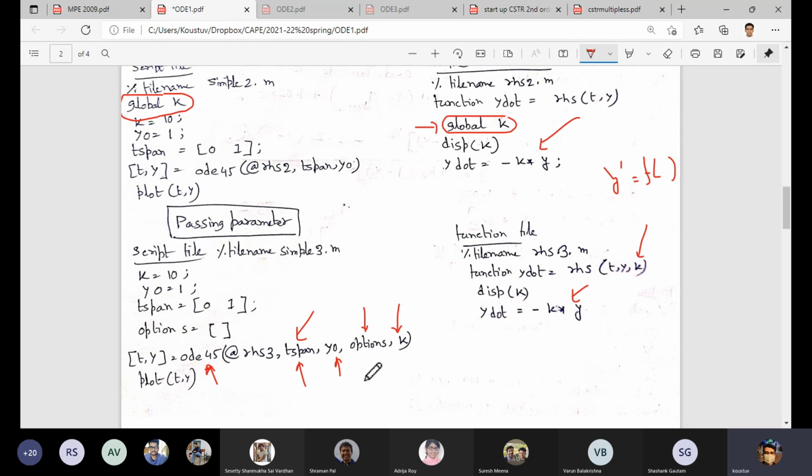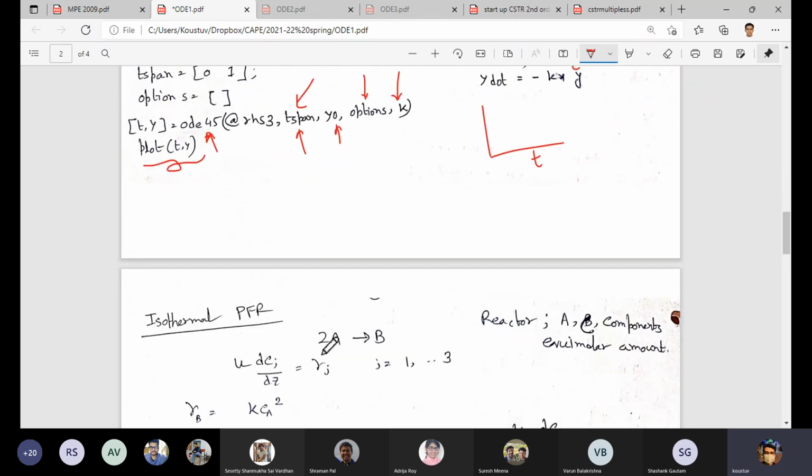But anyway, typically the thing that is available in MATLAB, just by calling this ODE45 and solving a system of equations or a single ordinary differential equation based on these input parameters like the time span, the initial values, and the relative tolerance if you want to change it, you can easily get the variations, the distribution of maybe temperature or concentrations or mole fractions with respect to time. So simple lines can be very effective, and we can get the desired results.